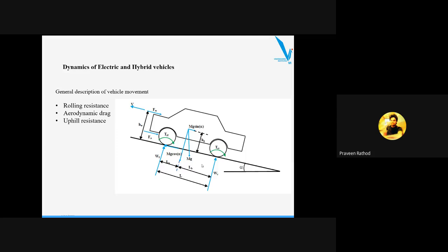Okay, so if you wanted to derive the equations for any vehicle, you need the dimensions. If you wanted to take the equation of motion along this direction, suppose this is a and this is b, if you wanted to take the moment about a, and the moment about b, you require the vehicle dimensions. Without dimensions we cannot write down the equations of motion. We cannot find out the reaction forces. That is very important.